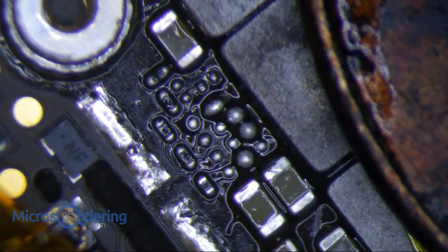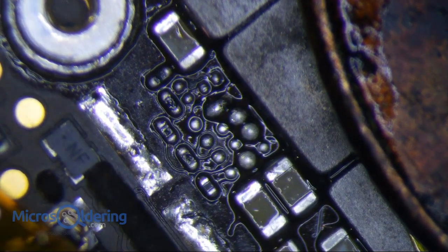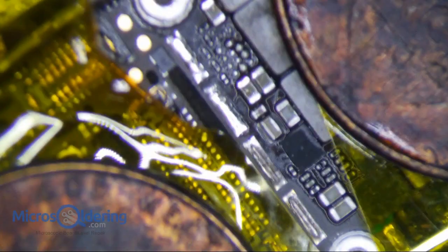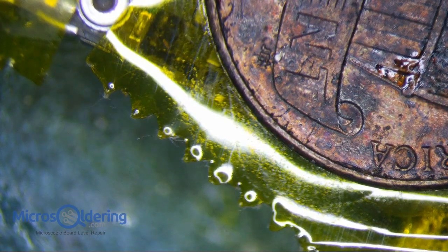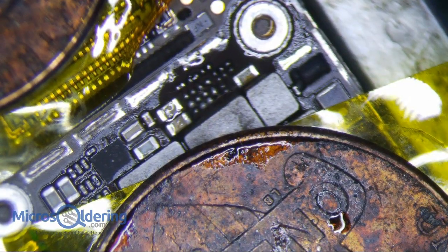So anyways, this chip is no good. That goes in the garbage pile. Sometimes I'll reball them, but it looks like it's that pad right there that caused it. My guess is that that pad is probably VCC main, because it's usually the high voltage that gets jacked up like that. So we will put a new one on, and I'm pretty sure we should be good after that.